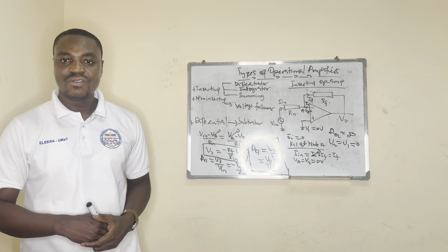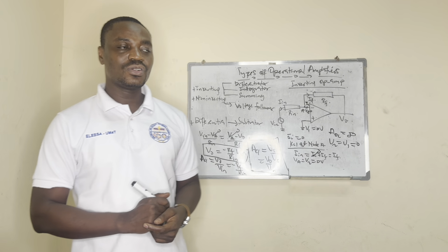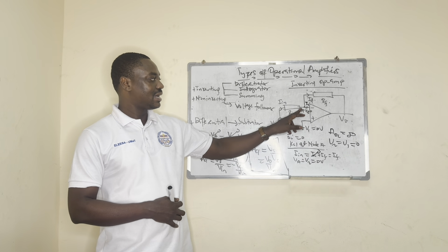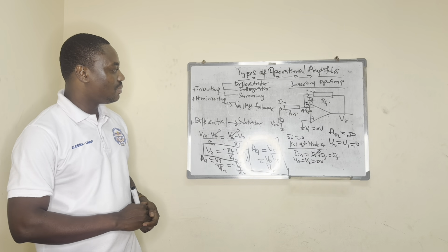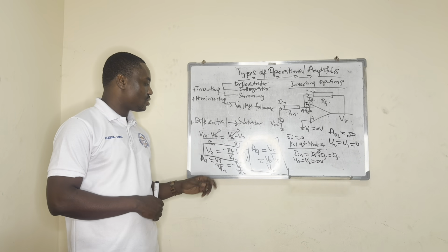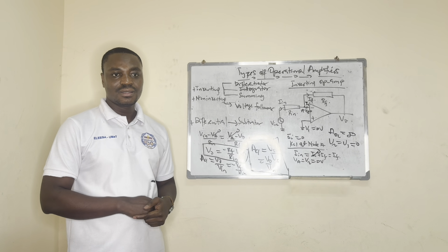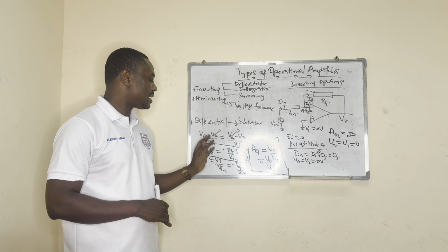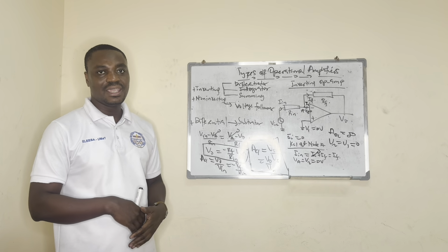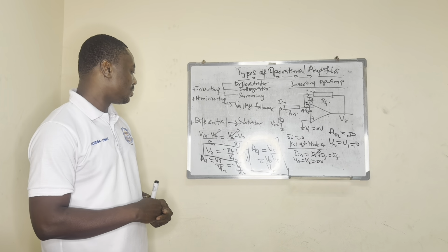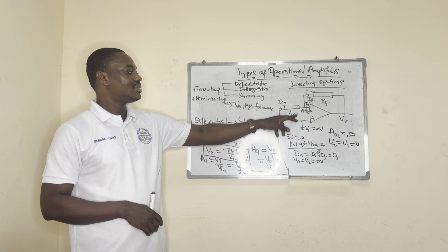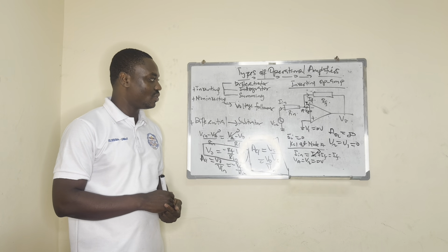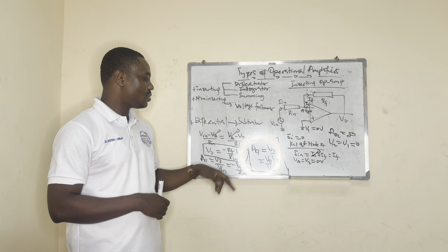So V in here is a higher potential, and the current is going to arrive at node A, so the voltage of node A becomes the lower potential. So the potential difference is going to be equal to V in minus VA all over Rin, which is the resistor between the two voltages. Then this will equal IF.